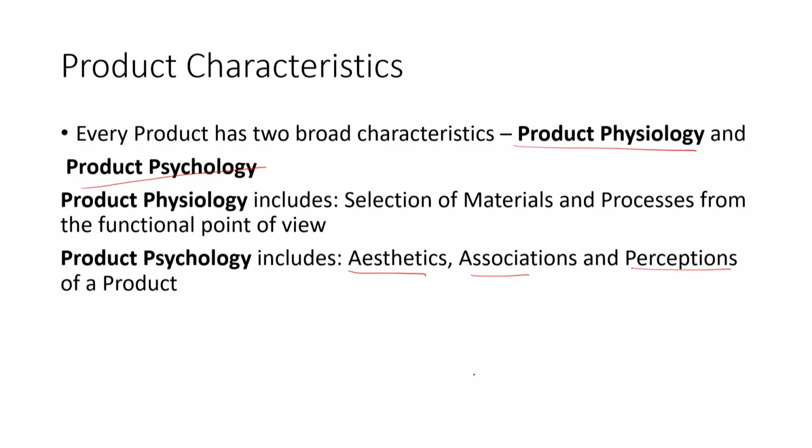Whenever we think of softness, does it mean that the system must be having high hardness value, like we know in mechanical context the Vickers hardness or Rockwell hardness, which only talks about the surface coating, the hardness of it, or does it mean that the product should be having a large modulus of elasticity? In fact, it is the product of the two that actually governs this.